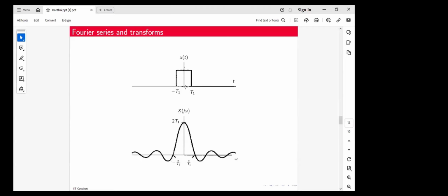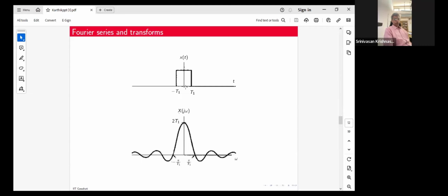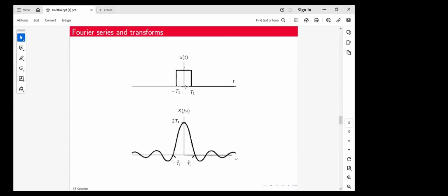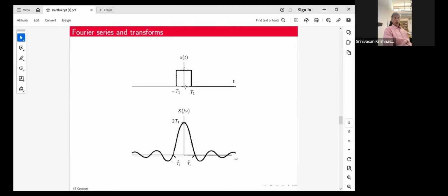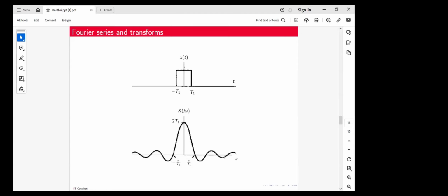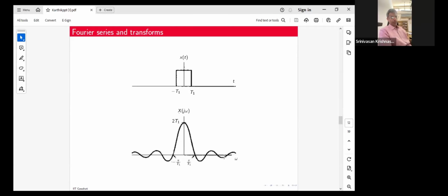For example, from my experience, if I take a 100 hertz square wave, I can get a full audio bandwidth within that. Suppose you take a 100 hertz square wave. The moment you have a periodic signal, your frequency response will no longer be continuous; you will have a discrete frequency response, because with a periodic signal you're looking at the Fourier series.